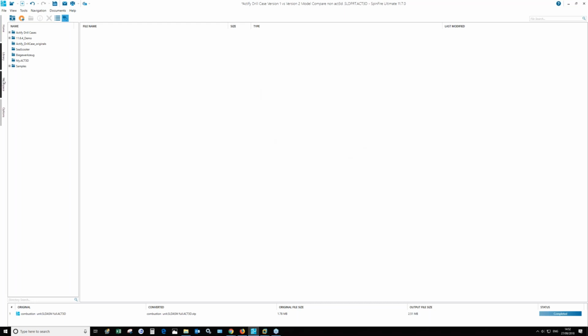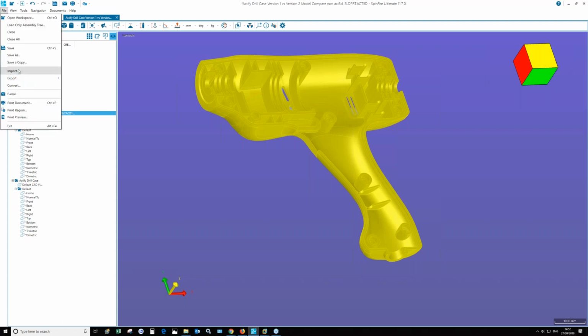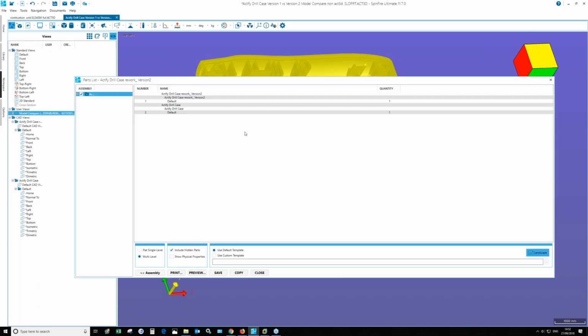So let's also, just to remind you, you can of course extract the raw information of the file. So if I went down from file to export, and I went to part list, and if I click, now of course I can see the assembly tree, now with a more complex model, where the sub-assemblies have their own parts, you would see the names, you would see the assembly tree structure start sticking out to the right to indicate that it's a sub-assembly or a sub-assembly, etc.